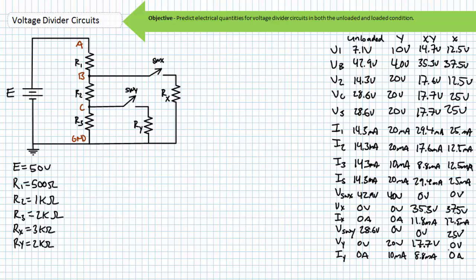Visualize circuits at the nodal level from the perspective of flowing current. If there is no choice of paths, those elements in the same paths are in series with one another, and current through them must be the same. If there is a choice in paths, those paths are in parallel with one another, and voltage across them must be the same.